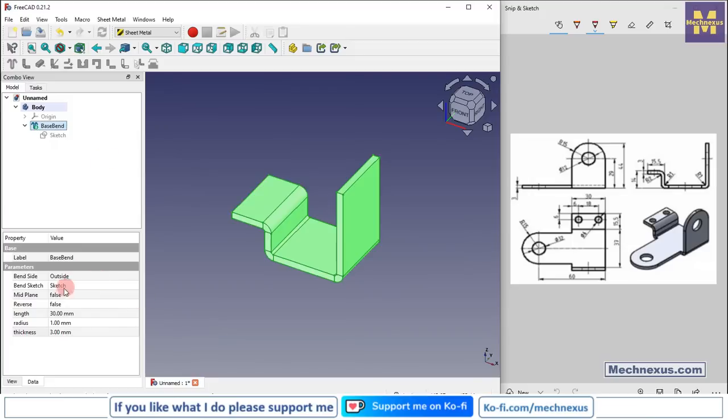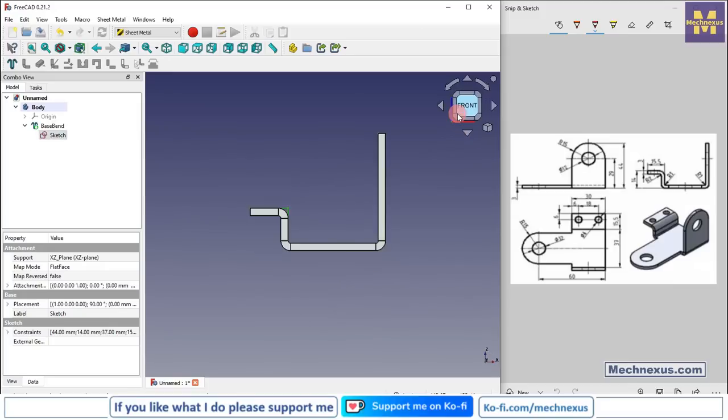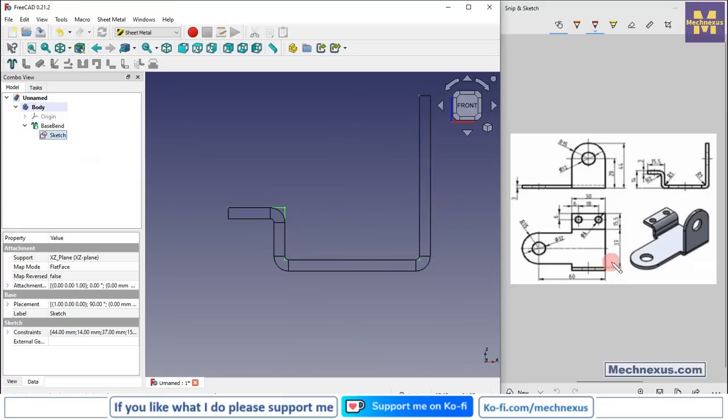Now here the bend is outside. We will create it to the inside because we have considered this outer diameter. So now if we see our sketch, here is a 37, and after that this is the thickness. So if we switch to the wireframe, this is our profile, because 37 is the inside dimension.